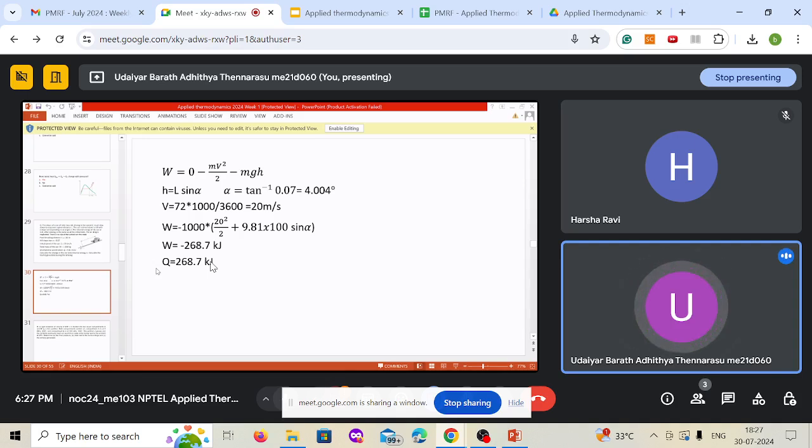So what does this signify? What is actually happening is you are at the top and you have to reduce speed, so you apply brakes. Normally you have shoe brakes which push on the disc or the wheel drums and try to reduce the speed. There is friction between these two, and this generates heat.